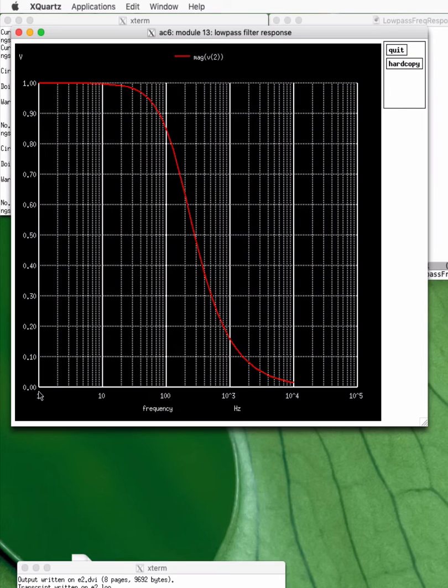So for low frequencies, we have a response that's basically equal to 1, as we suggested just looking at the equation. However, as our frequency increases, rather than having this very sudden sharp drop like we had when I was showing you those ideal filters, most practical circuits will have a gradual roll off. And so we roll off here, down, and then eventually we get very close to 0. Often the y-axis will be shown in decibels rather than linear, but this particular plot is just linear.